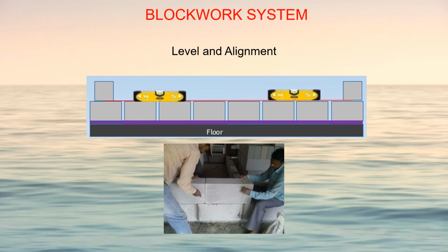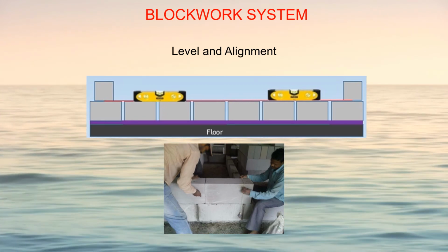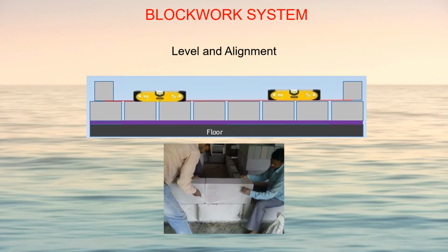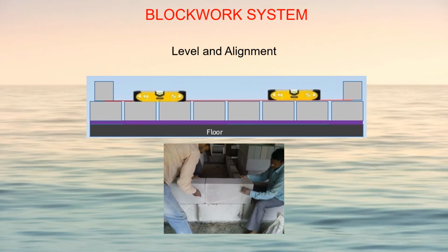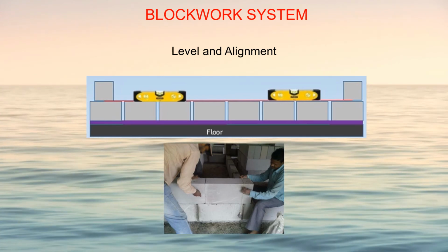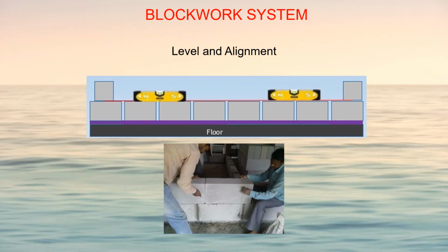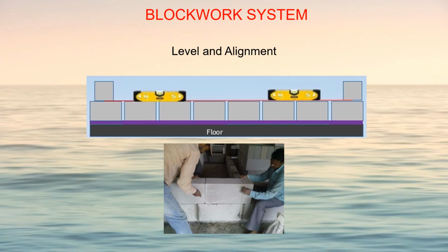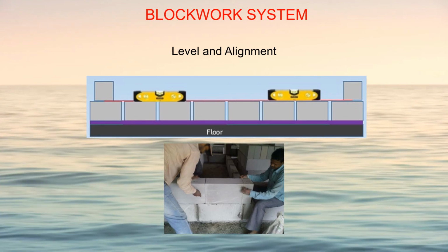and reused. Use a straight edge or spirit level on top of the blocks laid and check the top level. Make sure that the spirit level is in working condition and read the bubble carefully. Lay the last closure block in the course to close the bond and locate it to be near the center of the wall normally.